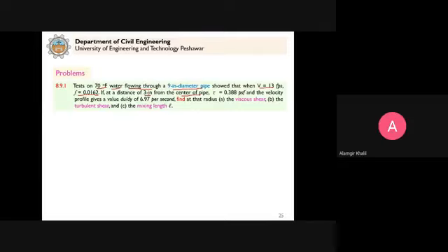So when you solve problems and r and y are written, you should understand how to calculate these distances. The total shear stress is given as 0.388 psf, pounds per square foot, and the velocity gradient du/dy is given as 6.97 per second.